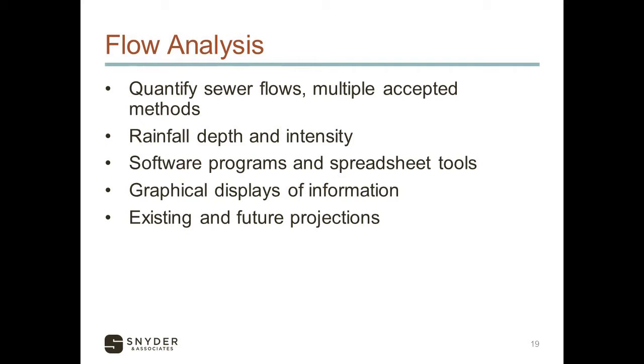Flow analysis. I've got a couple flow analysis techniques that I'm familiar with and just want to go through those at a really high level overview of what's out there and what we typically look at. Main goal, we're trying to quantify sewer flows, dry weather, inflow, and infiltration. We're using that rainfall depth and velocity to create ratios and project out values for different theoretical storm occurrences.